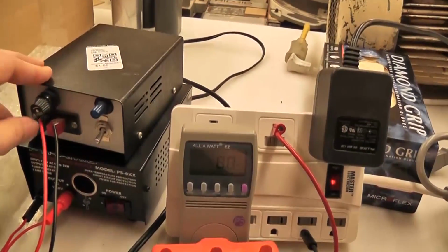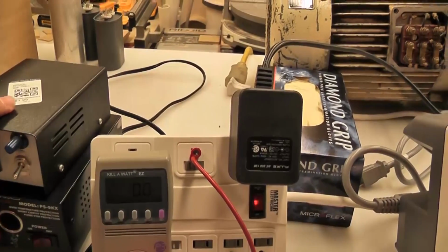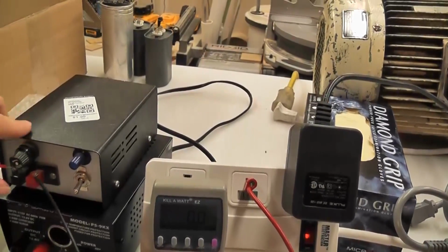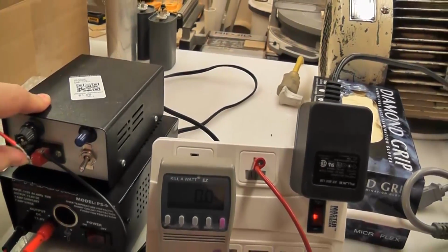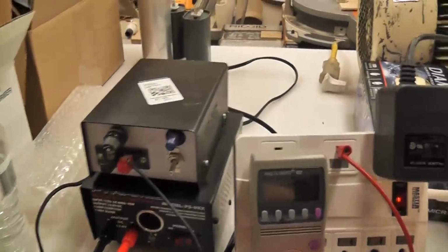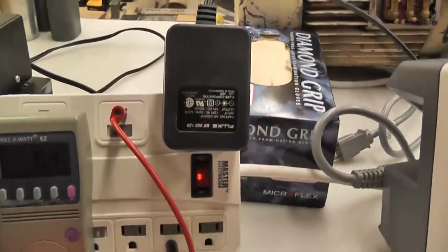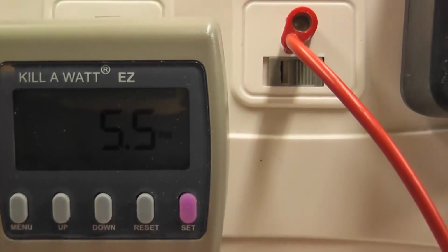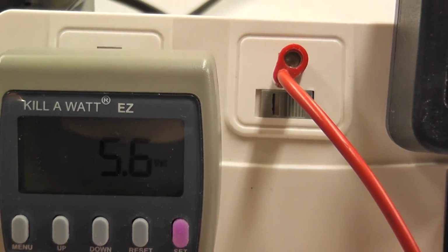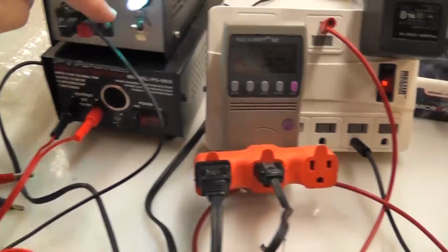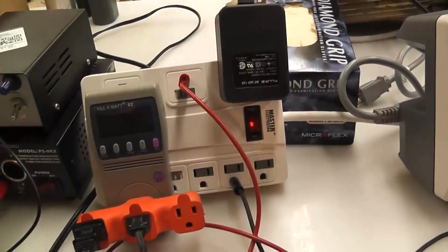And actually, why don't we do that right now? I'll just turn it off. If I can pull this out of here, we'll try it. Almost got it. I had a tripod and it broke. Okay, so the NST is unplugged. There's one wire there now. Let's turn it on, see what the watt meter says. So it draws about 5.5 watts or so, just with nothing connected to it. And that's typical. I think this bottom one draws about 6.6. Depends on what's in there.